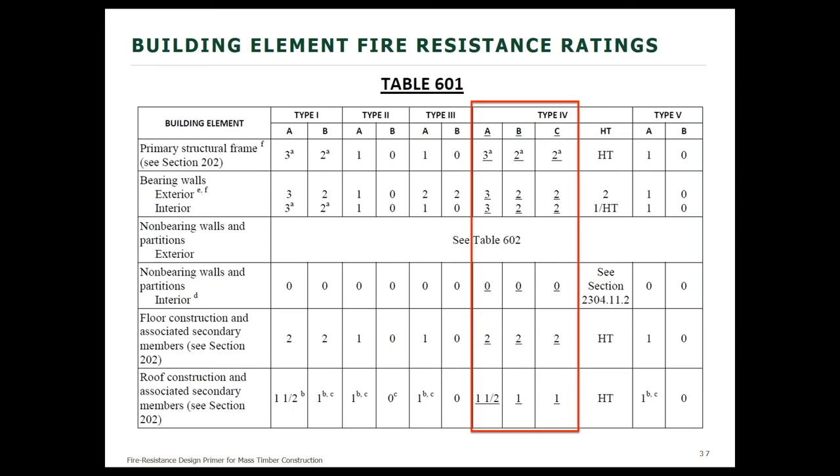So if you could jump back up to that slide you were on a second ago, there were a couple other questions with different types of construction. Is it true that Types 1 and 2 allow for heavy timber or mass timber to be used in Type 1 and 2 construction in certain instances? Very limited instances. I think there's a footnote relative to the table, and I can't remember what the specific criteria are, but it's typically up in the roof, where you can substitute out heavy timber in certain applications.